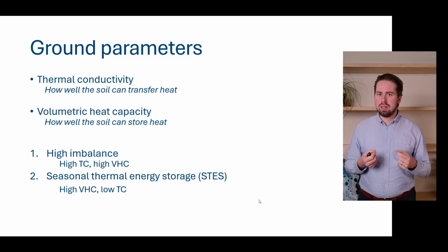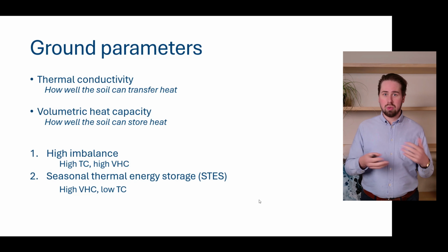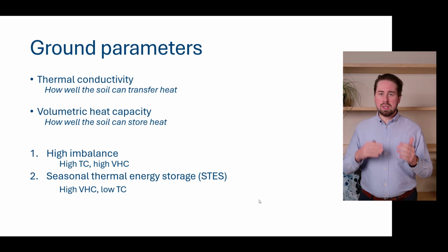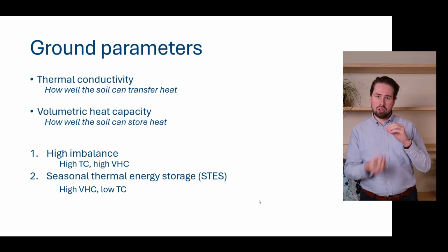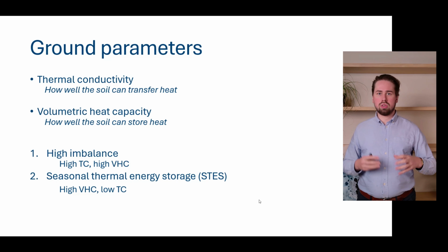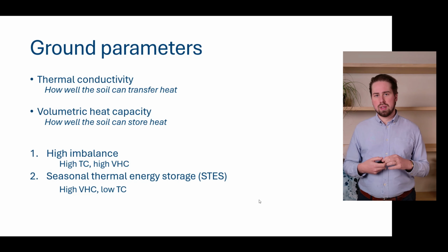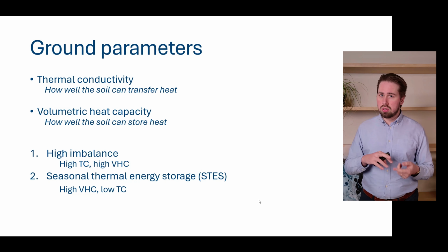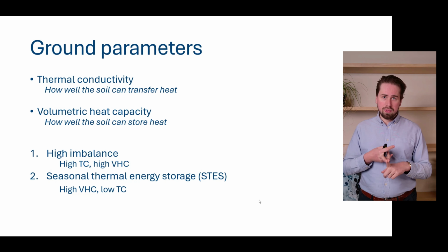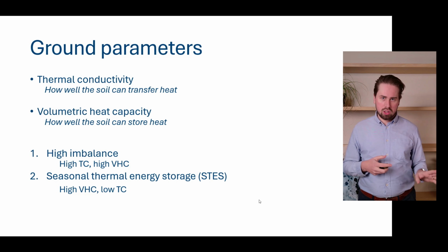Now, I also want to mention that your project location is what it is. You typically don't have the choice of what the ground properties are. But perhaps if you have different ground layers, you can design your bore field in such a way that you make sure you are in the ground layers where the thermal properties are as beneficial for your project as they can be. But this is just to show you the importance of certain elements. There is also the factor of porosity and groundwater flow, which also has an effect on your imbalance and so forth. We will discuss that later in this course.